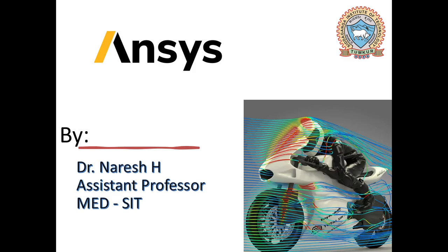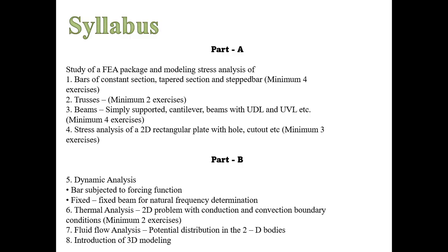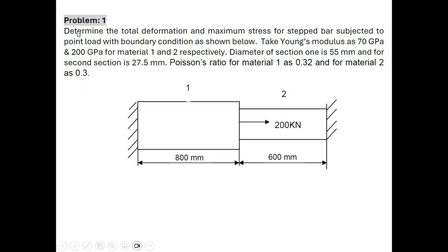We will be focusing on solving a static structural problem of a stepped bar using Ansys Workbench. So let's start. This is the problem statement. Determine the total deformation and maximum stress for stepped bar subjected to point load with boundary condition as shown below.